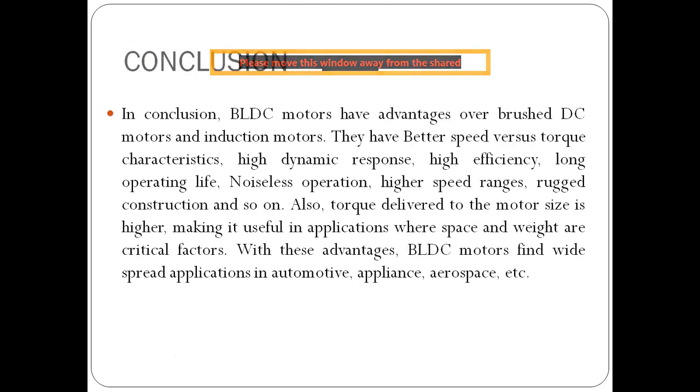Conclusion: BLDC motors have advantages over DC motors and induction motors. They have better speed versus torque characteristics, high dynamic response, high efficiency, long operating life, noiseless operation, high speed range, rugged construction, and so on.